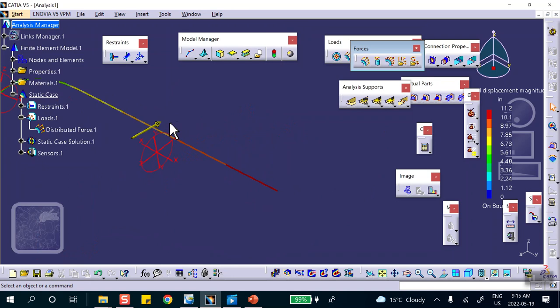Create the point on the geometry. Go to the advanced meshing tool. Insist that that node be transferred to the mesh. That's it. Okay? But you also realize that because the load is put there, this rest of the structure here,